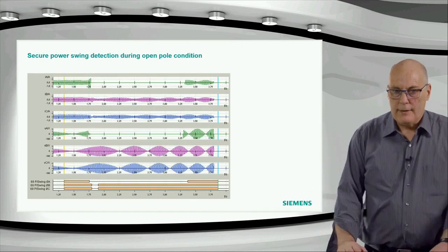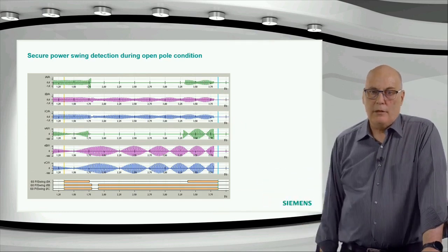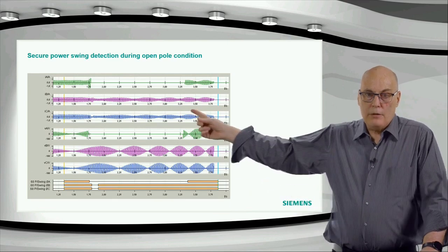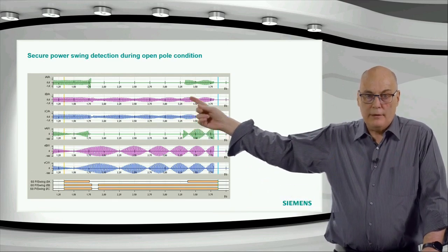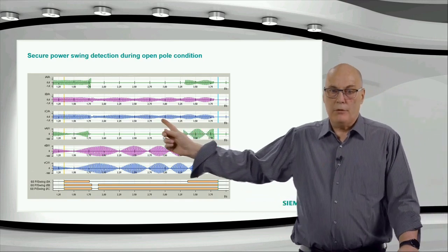It's one example. That's another example here. Here, the relay now does trip in the A phase, and you can see the dead time. You get the power swing continuing in the remaining 2 phases. And here, it's a more accurate simulation. You can see the power swing frequency is not constant.